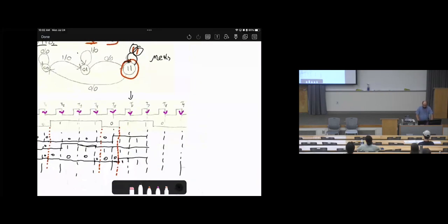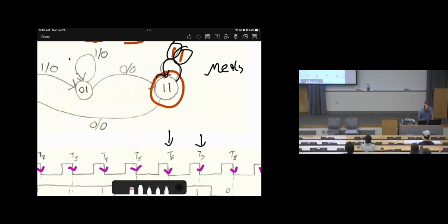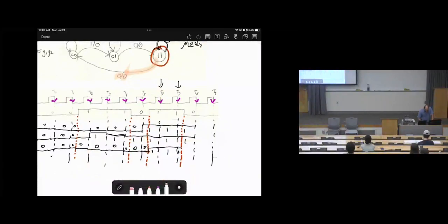Then, after that, at T7, it is 1, then it will be the same scenario. It will remain for the states, 1, 1. Look at the input, there is a mid-cycle change. So this might or might not affect. So we will see. Here the input will be 0. We are at 1, 1. At 1, 1, if the input is 0, the output will be 0. So it will move to 0. Okay, clear?